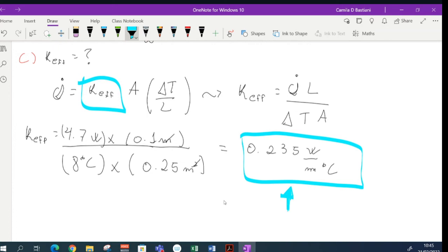We assumed that the thermal conductivities were constant, so there was no change of conductivity, and that we didn't have thermal contact resistance between the two layers. And we also did not consider radiation, so we disregarded radiation. So those are just some of the assumptions that you can make and state when you are doing your exams, okay? I know that Anthony likes it if you state your assumptions.